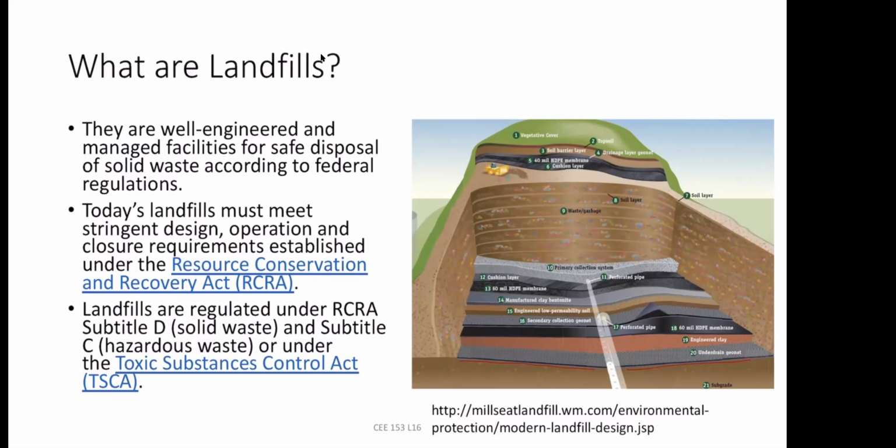So that means there is a low risk of groundwater pollution. But even though there's a clay site, you also have to think: is this an earthquake area? That means you don't want the earth to come out again. So that's why a lot of landfills have to be in a zone where you don't have accidental exposure in a future earthquake. And then you also have to think: is this a place where the groundwater is very near to the landfill? If it is, then you don't want to. Also, you want to put a landfill far away from surface water, because if there is a spill, the leachate is not going to go to that pollution.